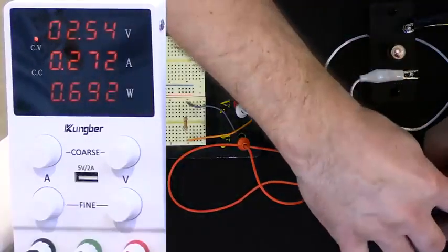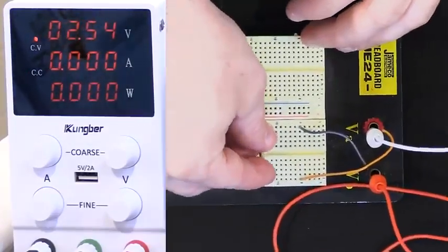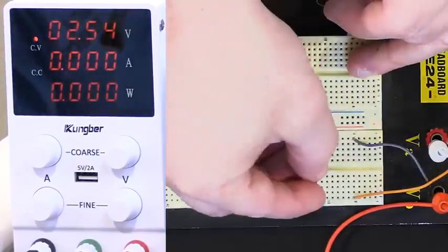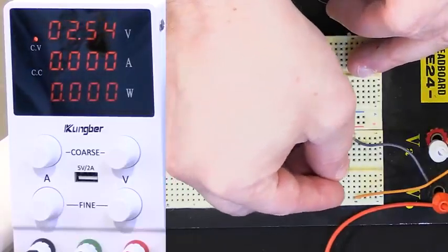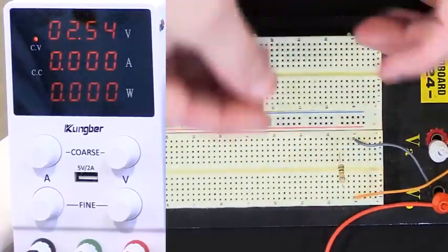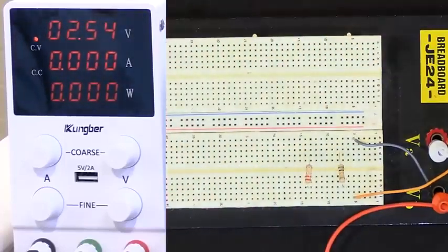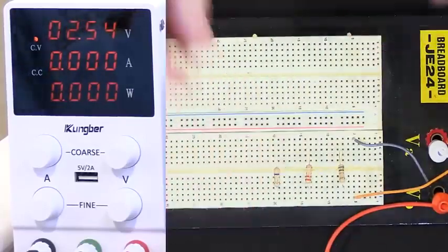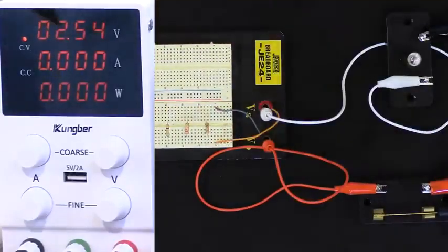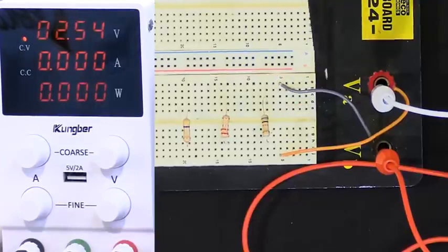Now I want to do it one more time, but in a slightly different way. I'm going to do them all in rapid succession. So there's the 1 ohm resistor, then here is the 2.2 ohm resistor, and then here we have the 4.7 ohm resistor. Now I have these two little jumper wires, and if I close it, nothing's going to happen. Why? Because the current is going into here, but there's nothing here. You have to have something connected to the other side.